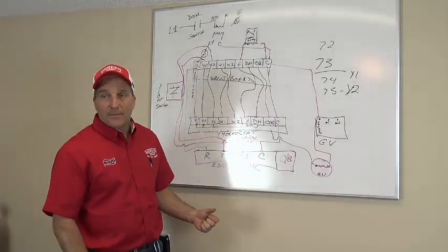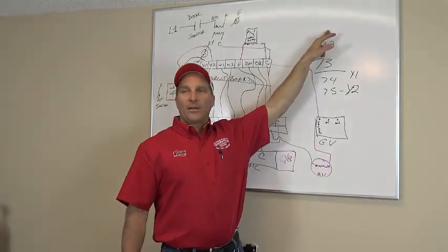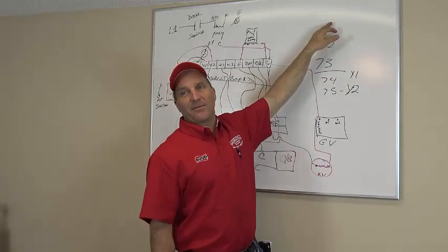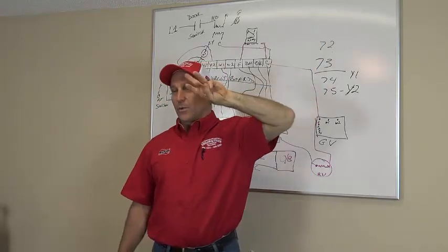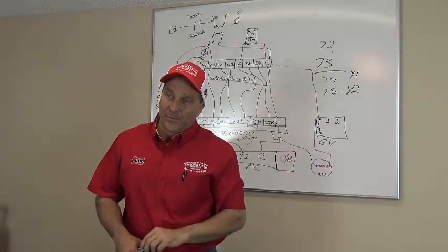So they do that. Slows the blower speed down, that goes from 72 to 71, right? Then it keeps going because it's still not satisfied yet. It goes to 70, then it's still not satisfied yet. It'll go to 69 degrees, 3 degrees below set temperature, and then it will stop overcooling the home.